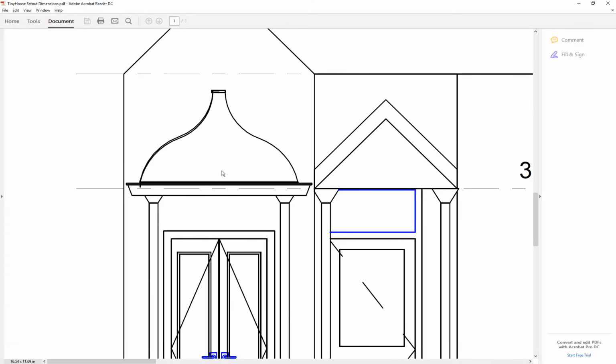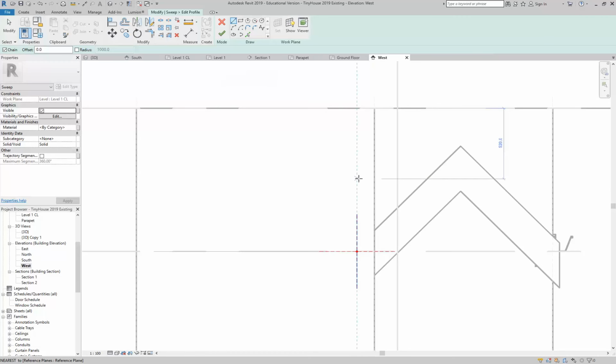So we've got this curve and then essentially another curve. There's at least two curves. Sometimes you need to use more to get the join, but you should be able to do it usually just with two curves. So with the arc tool, I'm going to go from that corner, and then I'll start just coming up again at 45 degrees. And about 700, we'll have to massage this, but it's about that.